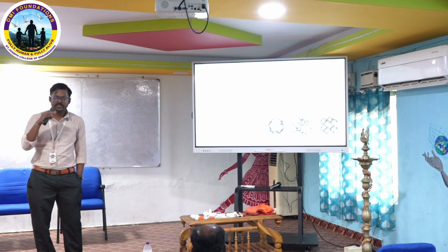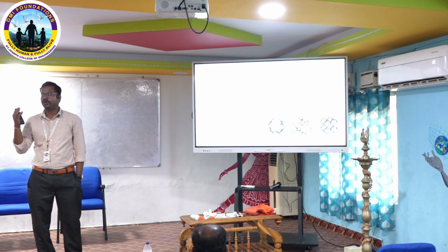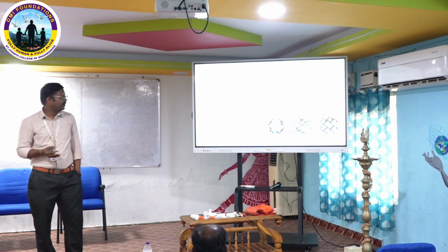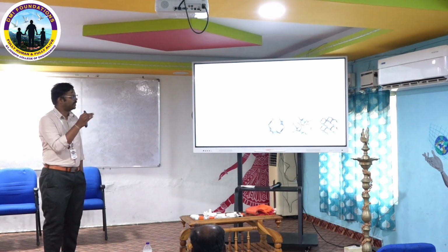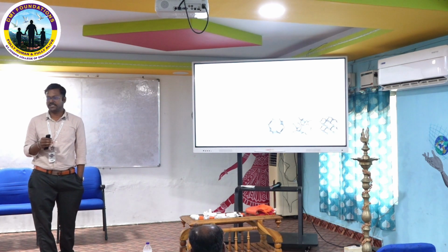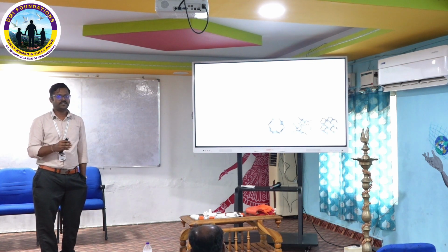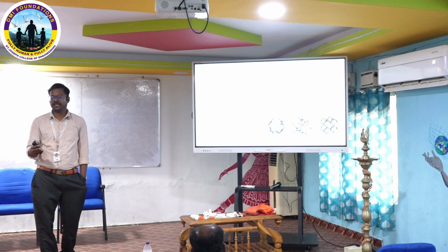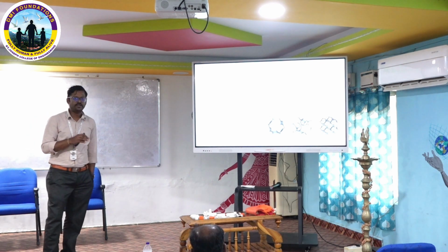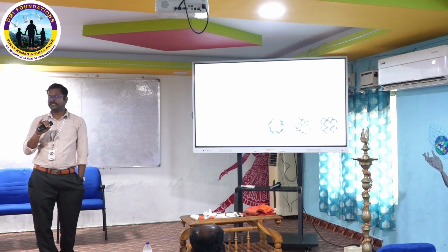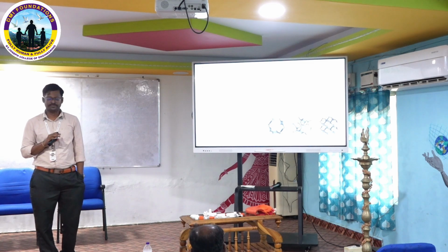So whenever it gets compressed, the struts bend and deform. So it gives higher energy absorption with minimum stiffness. When M is equal to 0 or above 0, it is a stretch dominated structure. So it absorbs more load in the elastic region. After that, it deforms plastically and gives minimum energy absorption. So it is more useful where strength is needed. In those places we can use stretch dominated structures.